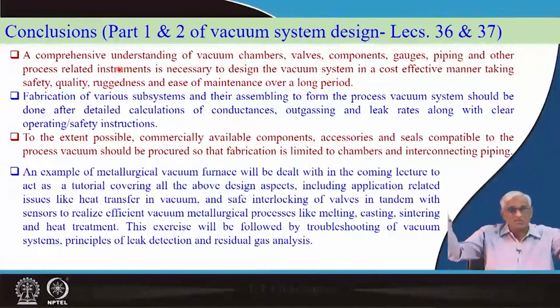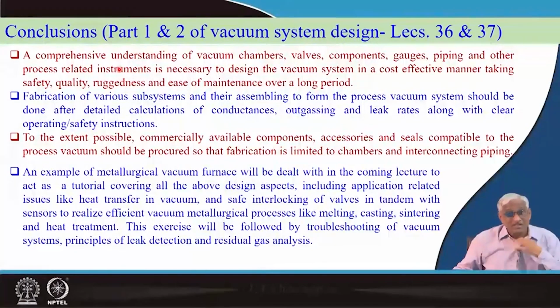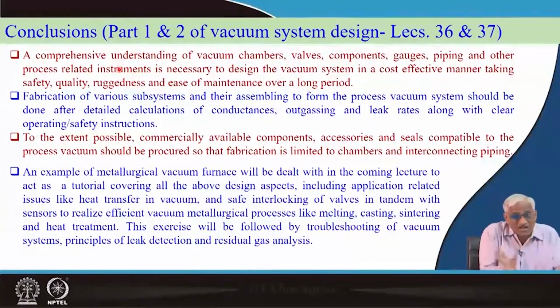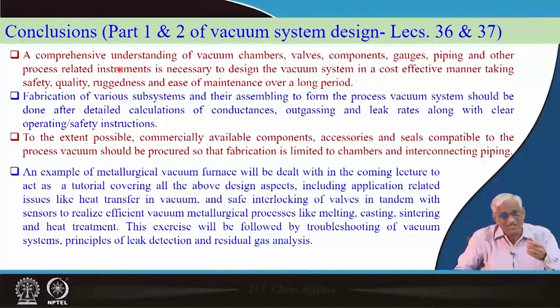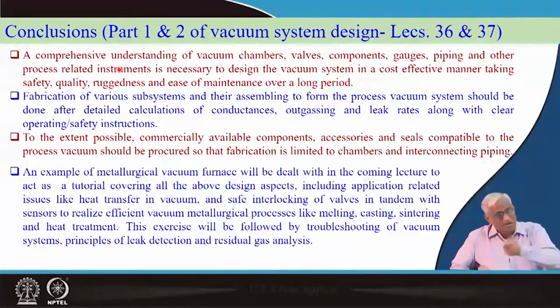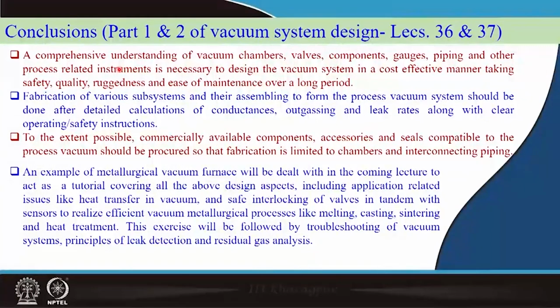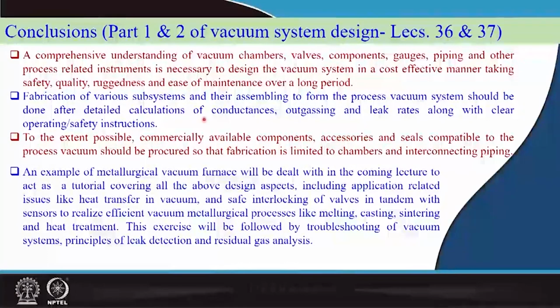In a very big space simulation chamber, if there is a sudden problem, it is so big it may even suck your shirt if you are suddenly nearby and you are in a hurry, you are in a worry, you try to close something and you are in trouble. Venting a large system, later we will see in the space simulation. If you make a mistake, you have vented when the sound is reduced, you suddenly open the main door, but still you might have vented it to a little over pressure. That over pressure into the door area is so enormous a force, it will hit your face. So, all these aspects the designer has to keep track of.